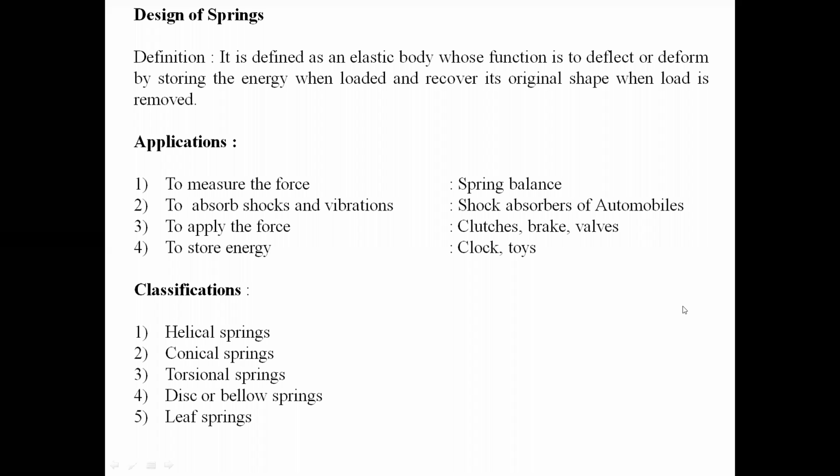In the spring balance, how much load is applied over the compression spring and how much is the compression of the spring, it is directly proportional to the force applied. So we can calibrate our load with spring compression. That is my first application: to measure the force, spring balance is used.